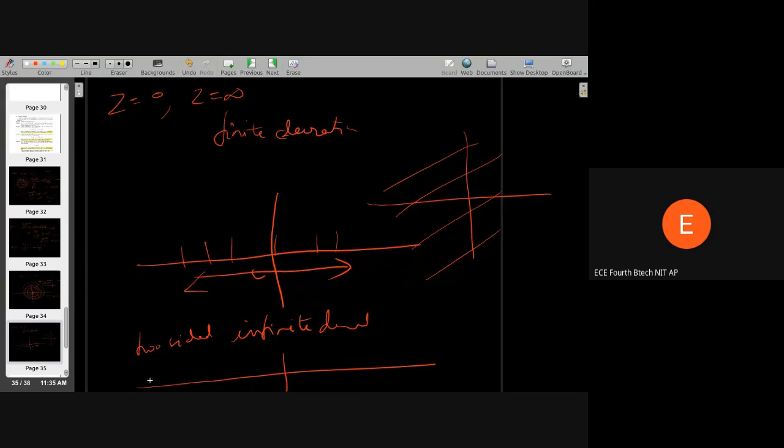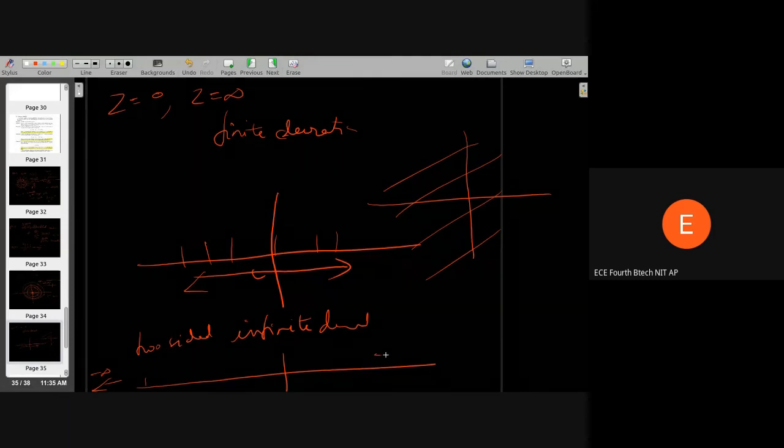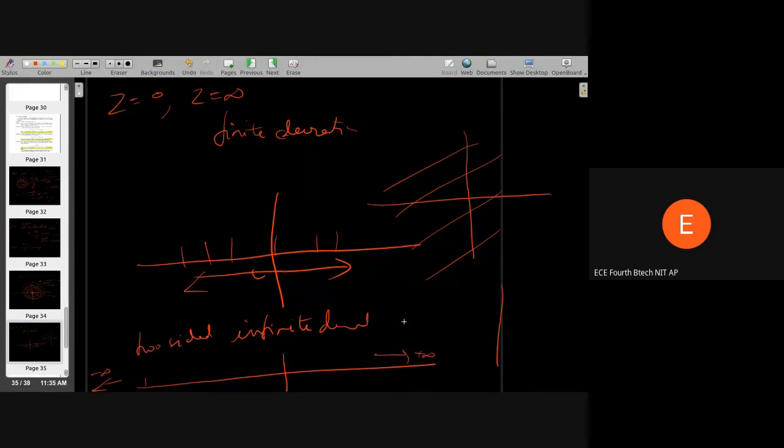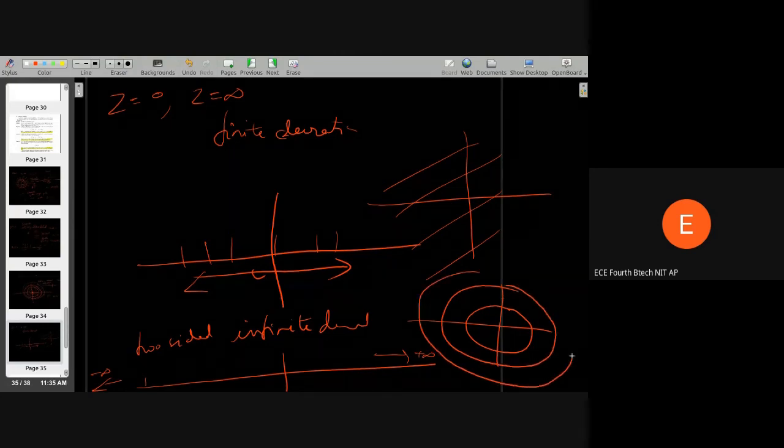But if your signal is towards minus infinity and towards plus infinity, both sided, then your Z transform will always be a strip between some poles. If this strip includes the unit circle, then your Fourier transform exists, your signal is stable, and so on.